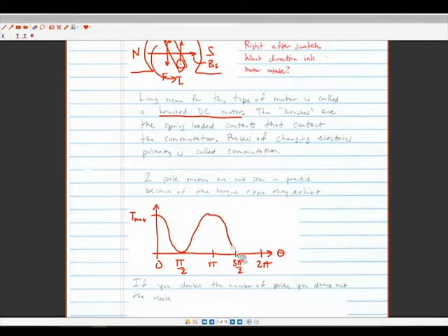And if you can imagine, as the video showed, it showed this really choppy behavior. So you can imagine if you had a motor that was so simple like this, it'd be extremely choppy in terms of the torque you'd get. Right? So it'd be really weak at 90 degrees rotation. It would be strong at 0 or pi or 2 pi angle of rotation, right? So engineers are pretty smart people. We've figured out ways to get around this.